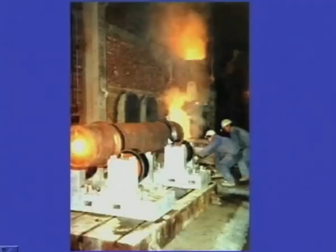Here I am showing a photograph where the centrifugal casting is in progress. Here we can see the metallic mold, and here we can see the rollers, and the molten metal is poured through this end, and it will be occupying all along the length.